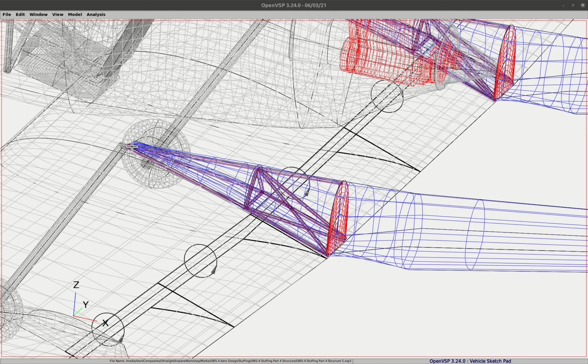So obviously this steel structure in here, which would be something like 4130 steel tubing, chromoly, would be welded together. And like I said, probably covered with an S-glass covering. And it would be all faired in here to reduce interference drag. And doing this, I don't have to do any cutouts of the wing. So the skin can come all the way out here on the wing, so I don't have any cutouts there. So that should help carry any torsional loads very nicely.